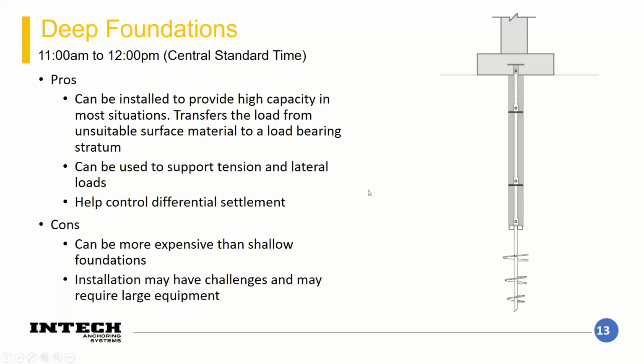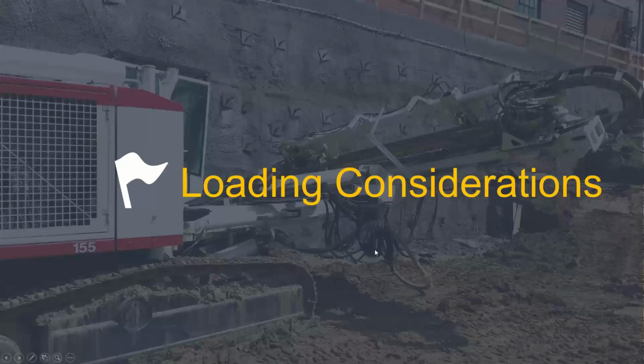So helicals and micropiles actually use relatively small equipment, which helps mitigate some of those challenges. But if there are difficult soil conditions, it still could be problematic either way. So let's keep going here.